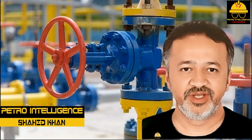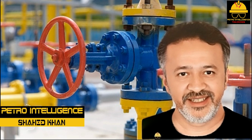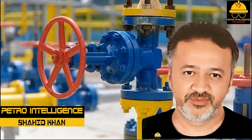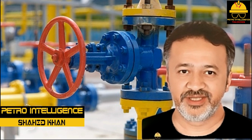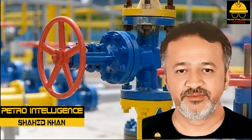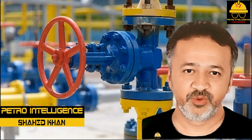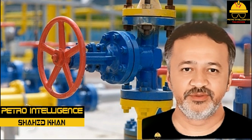Process fluid enters the globe valve and is directed through a 90 degrees turn to the bottom of the seat and disc. As the fluid passes by the disc, it is evenly dispersed. Globe valves must be installed properly to work efficiently. If the valve is installed backward, it will tend to wear unevenly and push the flow control element down.